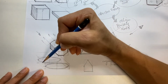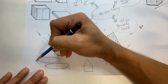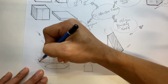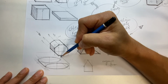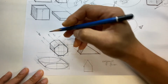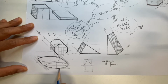Now what you need to do is to join them at the edge. So this oval, the furthest edge which I can use to draw a 45 degrees line, you look closer to the object, and then I'm going to touch the edge. Now where this line touches the edge, this will be the edge of the oval. And then for the lines on the right hand side, I'm going to draw horizontal line closer and closer. The moment it touches the edge, this will be the edge of the 3D drawing of the oval. And then do the outline. And then the base.